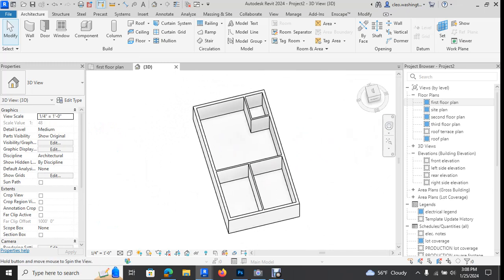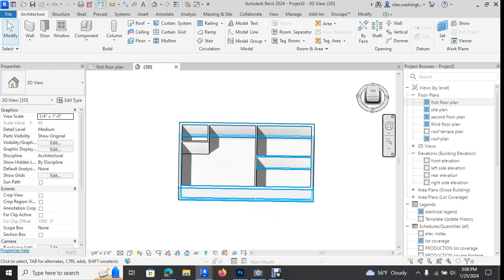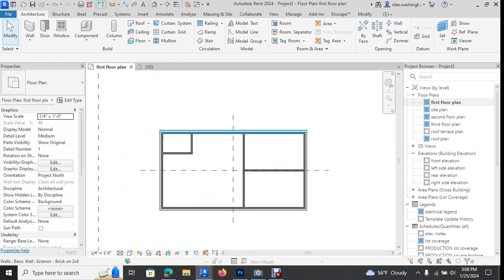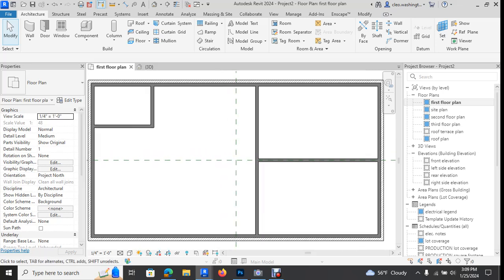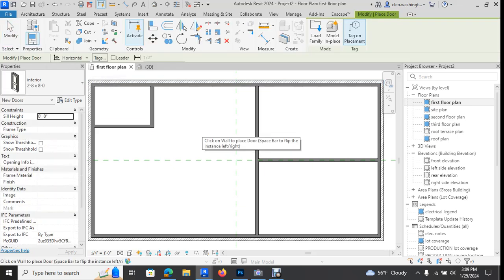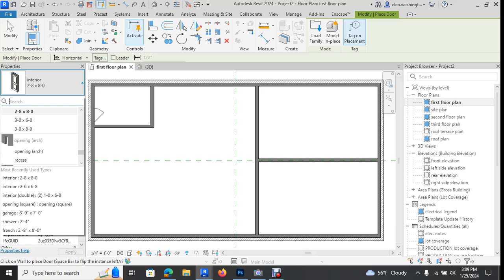So next, let's go ahead and apply some doors. Let's go back to the first floor plan, and let's put some doors in that have been shown according to the plan that's documented in the book. All right, so for doors, you can either come here and click doors, or you can type in DR, which is what I like to do, okay? And let's see, what type of doors are they wanting us to throw in here? I think they said something like 36 by 80. Yeah. 36 is 3 feet. So you want at least a 3/0 door. Let's go with a 3080 door right here.